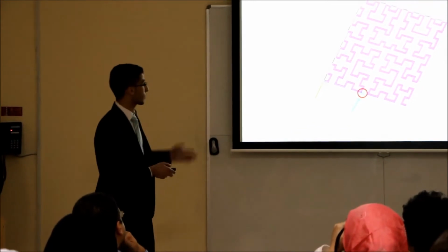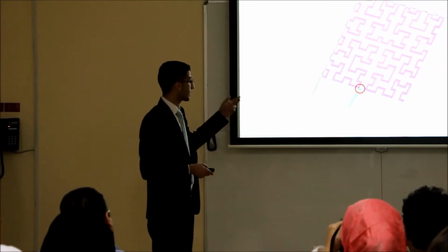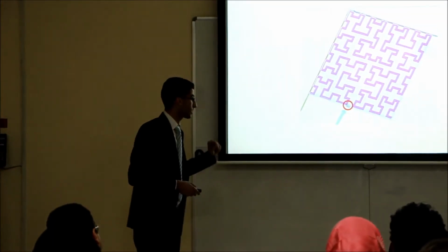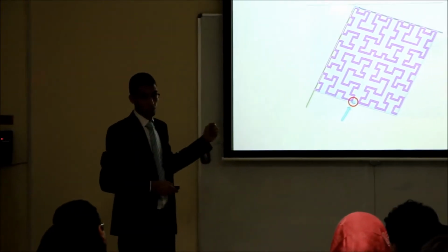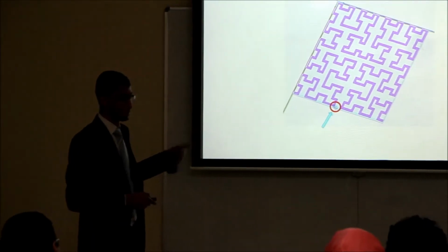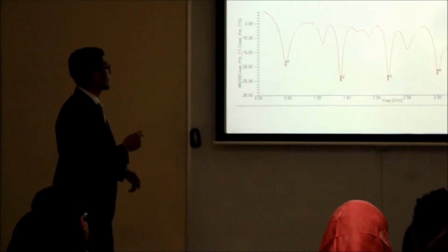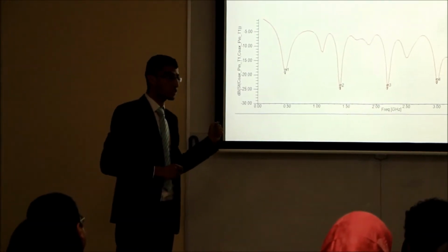The simulation was done on the optimum parameters, which are the length, the thickness of the PCB, and the thickness of the patch itself, which were found by equations. However, the feed point and the material were found through the simulation from different feed points and different materials, which we're going to discuss in the next slide. First, we measured our antenna performance.